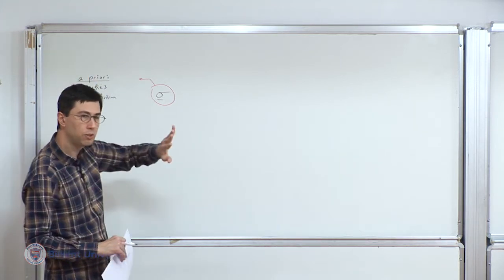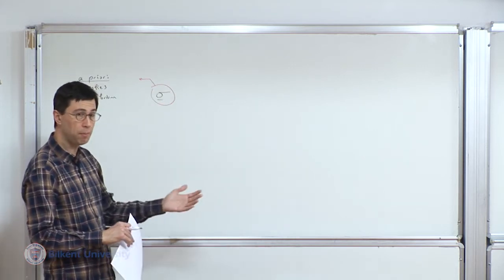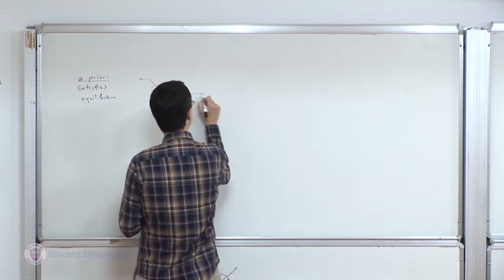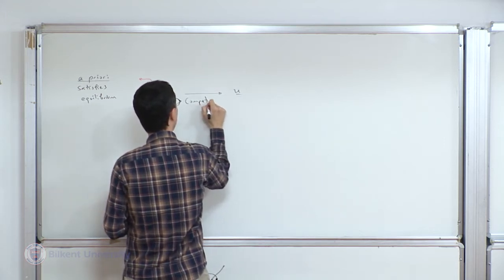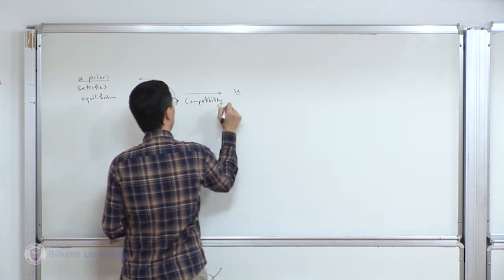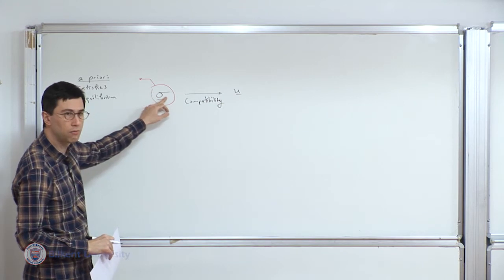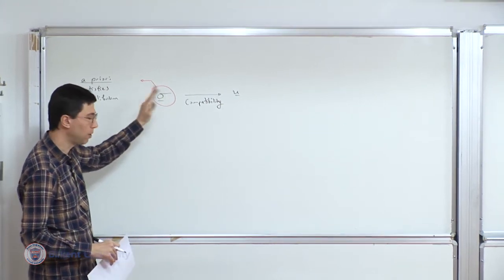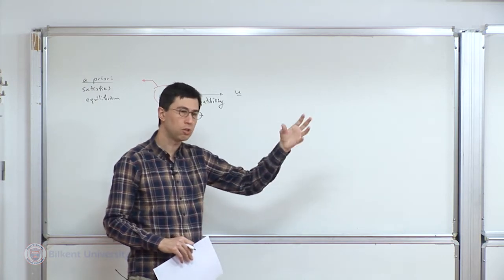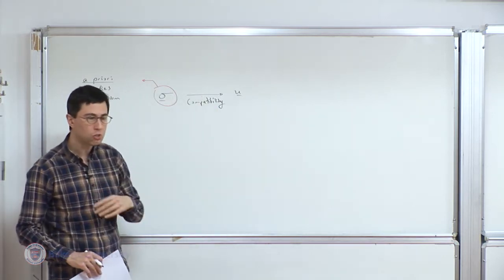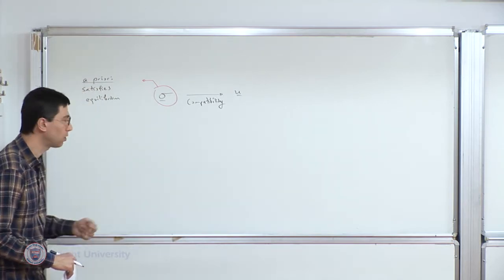But contrary to the displacement-based approach, where compatibility is satisfied from the outset, in this case we are going to enforce it. So in a sense, compatibility is the key equation that will allow us to restrict the particular form of the stress that we propose. In the displacement-based approach, we start with a simplified form, look at the symmetry of the problem, calculate the strain and stress, and enforce equilibrium. We close the loop, and we get the particular form of the solution.